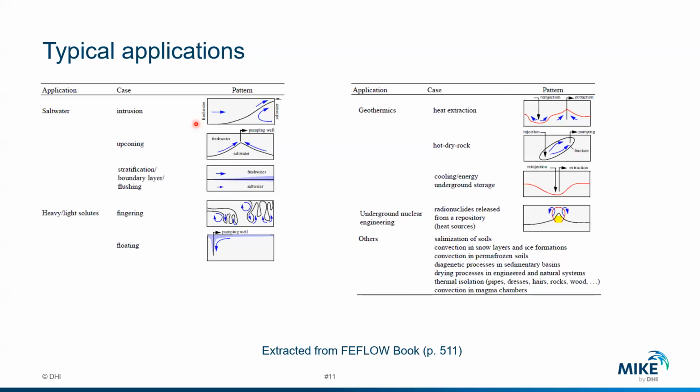So you have a typical freshwater aquifer and the sea level, and there is an intrusion of the sea into the coastline. There is a certain equilibrium between fresh water and salt water, and depending on human activity, this equilibrium could be broken. If you have pumps in this freshwater aquifer, the equilibrium will be broken and there will be more intrusion.